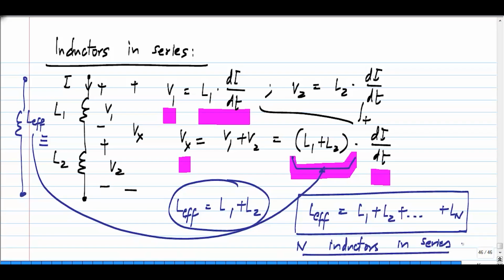Okay, now these are all elementary results. What I want to emphasize is that we start from the basics, that is KCL or KVL. Here, in case of series combination, Kirchhoff's current law tells us that the same current flows through all the elements. Kirchhoff's voltage law tells us that the voltage across the ends of the combination equals the sum of individual voltages. Then we combine these consequences from Kirchhoff's current law and Kirchhoff's voltage law with the IV relationship for each element and deduce the nature of the series combination.